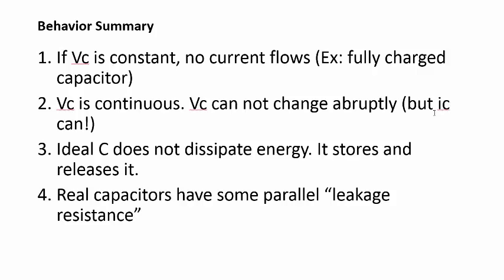So, okay, voltage cannot change abruptly in a capacitor, but current can. An ideal capacitor does not dissipate energy. It stores it and releases it. So it's not going to give off heat either like a resistor does.